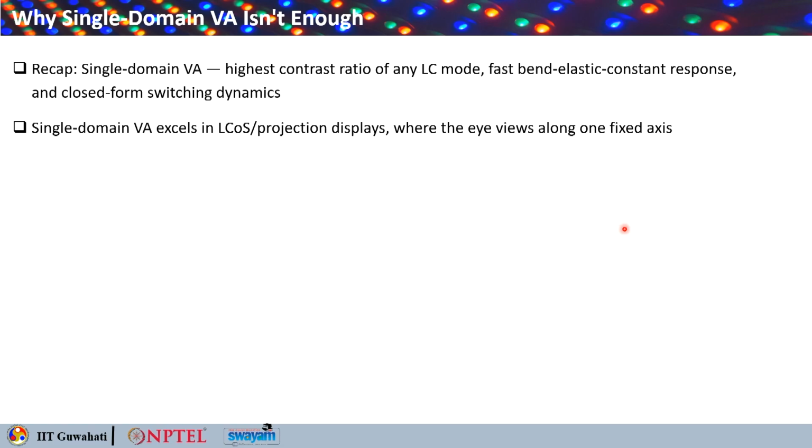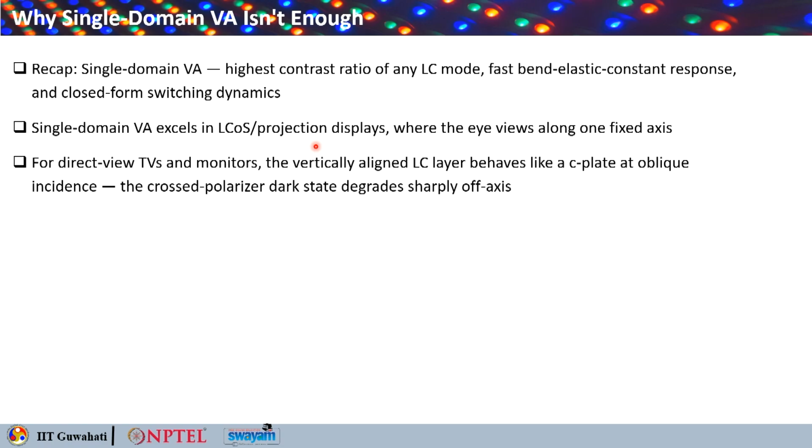Okay, so single domain vertical alignment is good for liquid crystal on silicon or projection type small displays where the eye views only along one fixed axis.